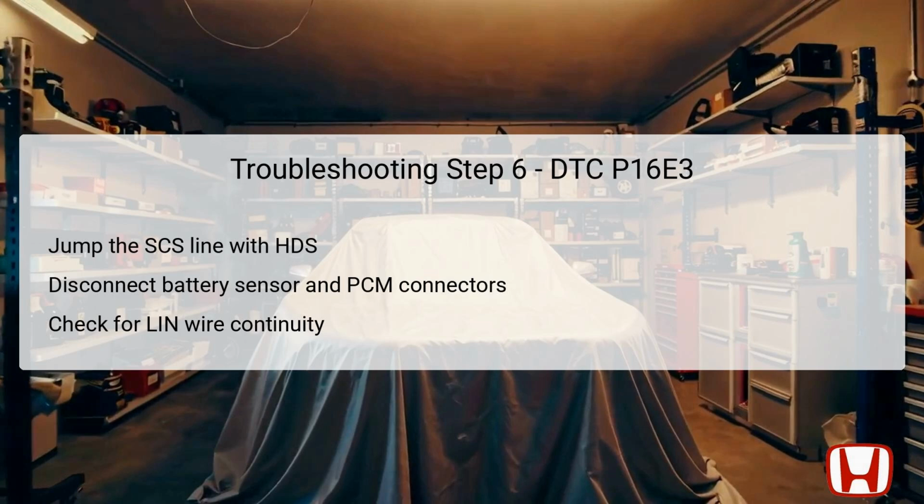Confirming the integrity of this LIN communication wire is essential, as a successful continuity test indicates no open circuits in this line. If continuity is not found, this infers there is an open wire between the battery sensor and the PCM, warranting further investigation and correction.